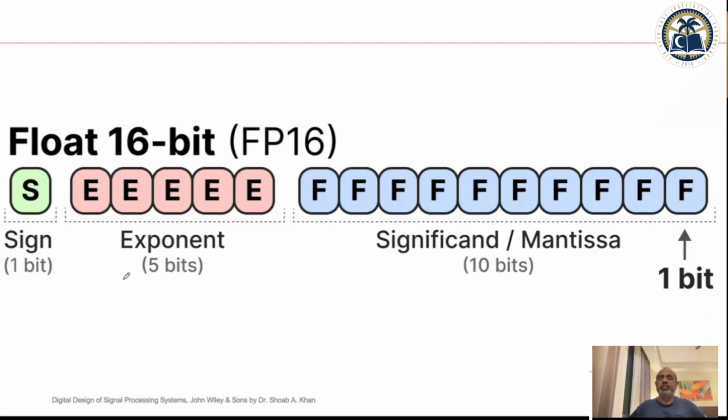So converting them into fixed point is almost impossible, because if you have such a dynamic range of numbers, then there is no point in fixing a decimal, because sometimes the entire part is integer, sometimes the entire part is fractional. So how should you decide? And there is a variable which is just changing its value. So usually fixed point does not even become an option.